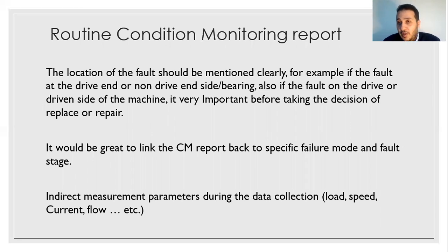We have motor bearing failure. Which bearing, the drive end or the non-drive end? Mostly in the motors, when one of the bearings fails, you replace the two bearings. But you have to be more specific when you talk about your recommendation. You have to state what the machine is and what the bearing is, drive or non-drive end.